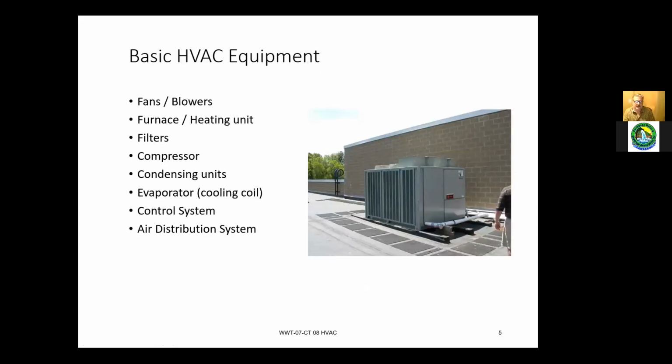Some of the basic HVAC equipment: fans and blowers, which need to move the air, the furnace or heating unit, and filters. Many times the filters are an operator's job to change. So you'd look at your manufacturer's specs for the required frequency and change those. Filters do take some time to go around your facility and change, but they can extend the longevity of your equipment by many, many years. Having clean filters is a must.